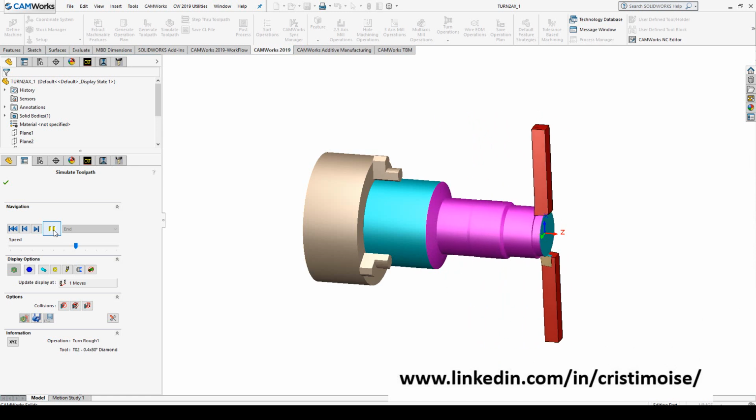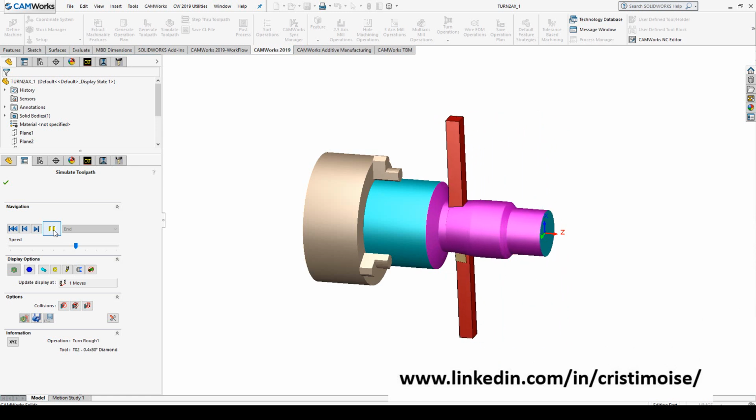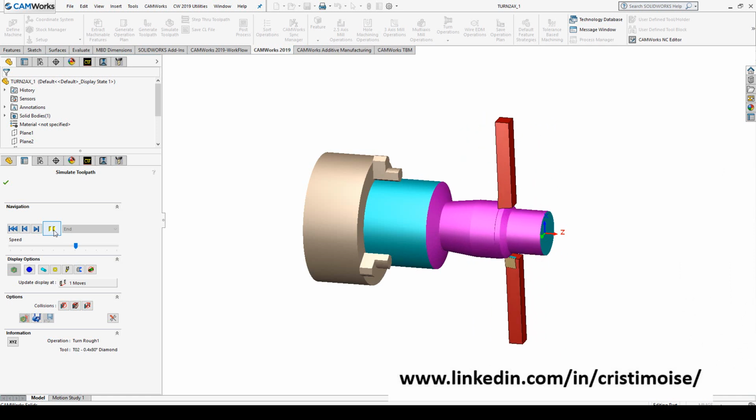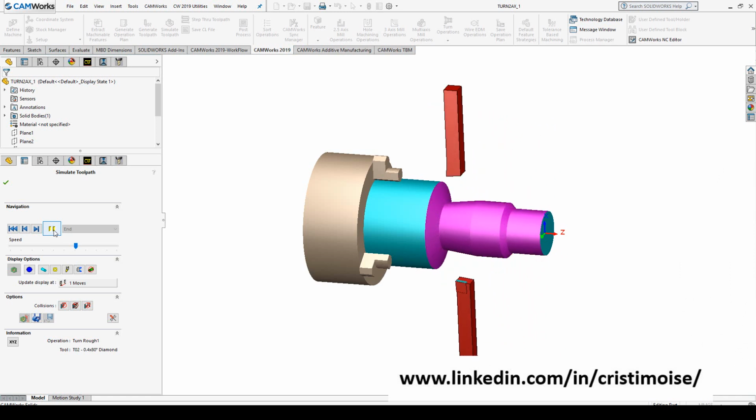The user can assign one tool as a primary tool to generate the toolpath and a different one as the secondary tool to gauge check the toolpath. Using two tools to machine the part model at the same time helps you double the feed rate, and of course significantly reduces the machining time for your parts.